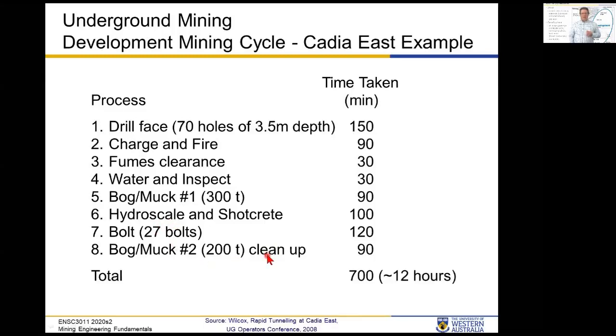And that's it. So it all adds up to just under 12 hours. So that will advance 3.5 meters every 12 hours. So you can see it's a fairly slow process. Obviously, these will vary from site to site, how many holes you have, how much ground support you need, etc.